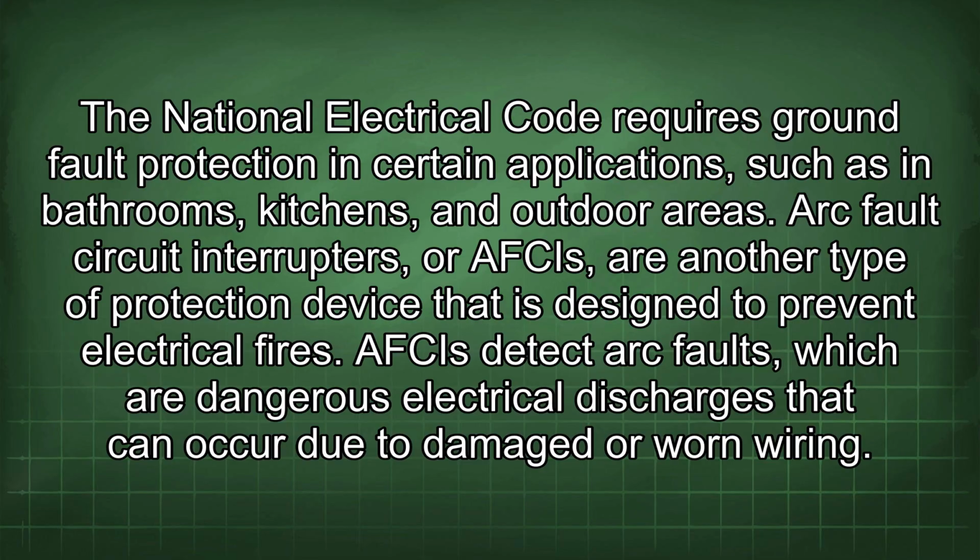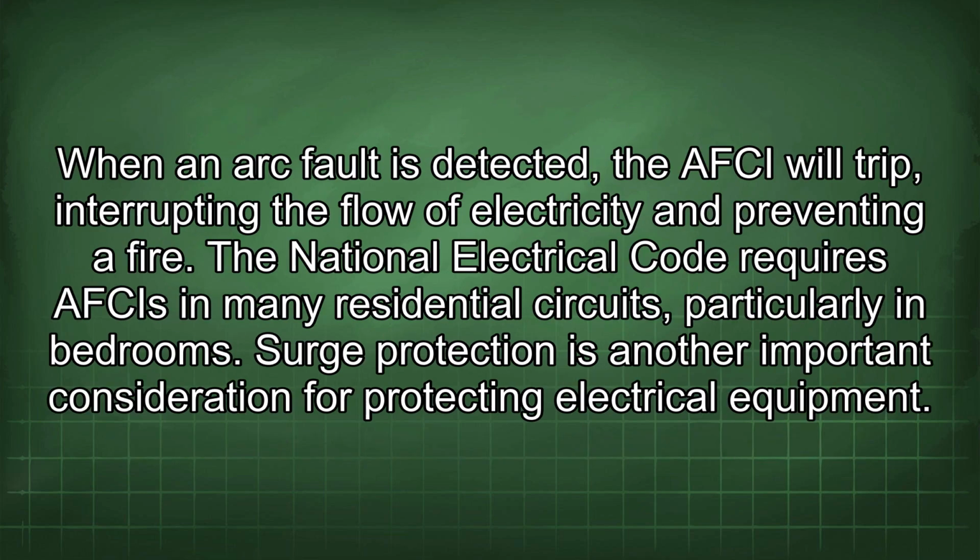Arc fault circuit interrupters, or AFCIs, are another type of protection device that is designed to prevent electrical fires. AFCIs detect arc faults, which are dangerous electrical discharges that can occur due to damaged or worn wiring. When an arc fault is detected, the AFCI will trip, interrupting the flow of electricity and preventing a fire. The National Electrical Code requires AFCIs in many residential circuits, particularly in bedrooms.